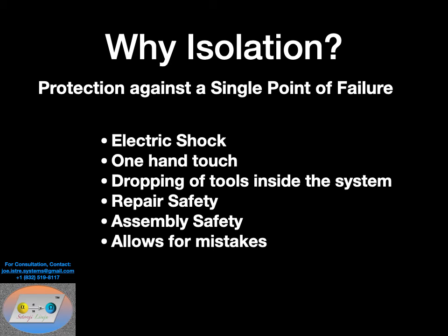That way, with two hands, an electric shock can go across your heart and give you a larger danger of cardiac arrest. However, if you're touching it with a single hand, then there's no circle it can make through your heart from your hand, and that way it's a safer setup if you design for a single hand touch that is a fail-safe.